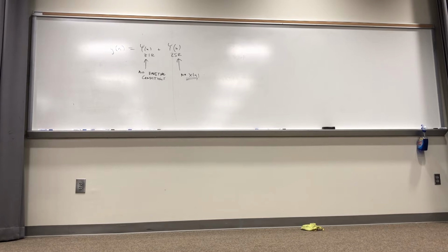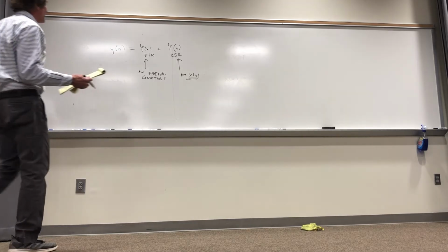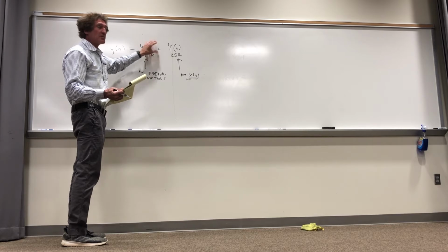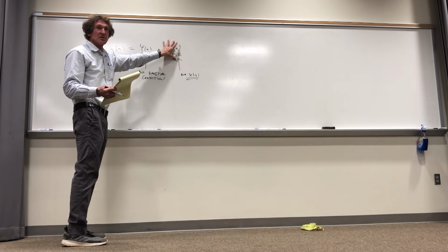I'm trying to say when you get the values of y of -1, y of -2, that's the initial energy in the system. Even though our Z transform starts for values of n greater than or equal to 0, the way that you get initial energy, call it that, into the system is through values like y of -1, y of -2. I'm going to show you this in a second, all right? Just understand this. You can break the total output into the response to the initial conditions, or initial energy, plus the response to the actual forcing function x of n.